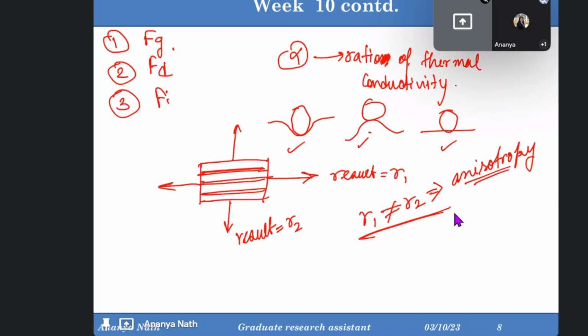We cannot really get rid of this problem. Some types of processing technique will always result in anisotropy. You can change the isotropy or anisotropy to some extent, but you cannot transform anisotropic nature to isotropic by changing some process parameter, never.